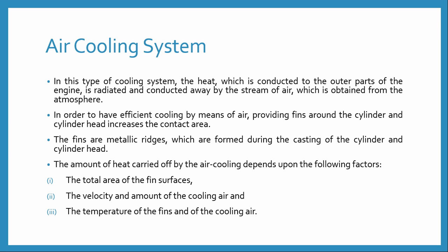In order to have efficient cooling by means of air, fins are provided around the cylinder and the cylinder head, which increase the contact area.